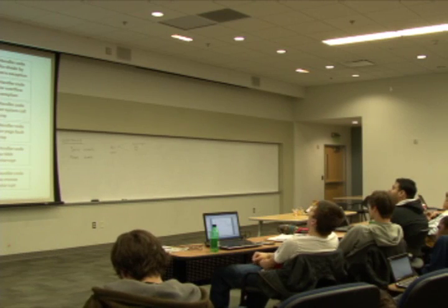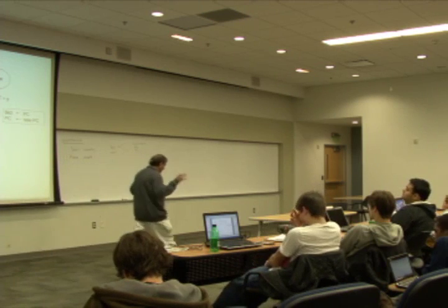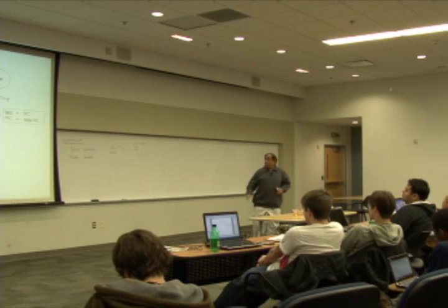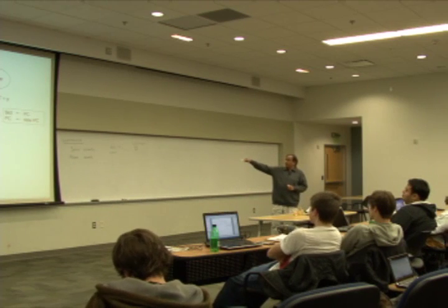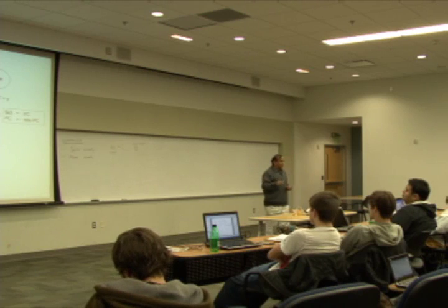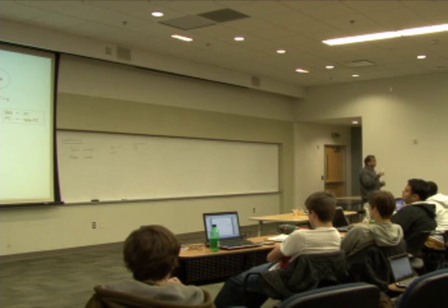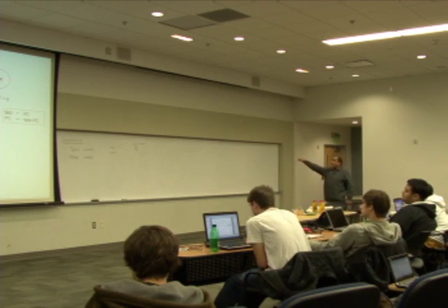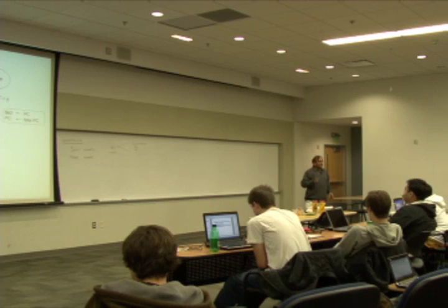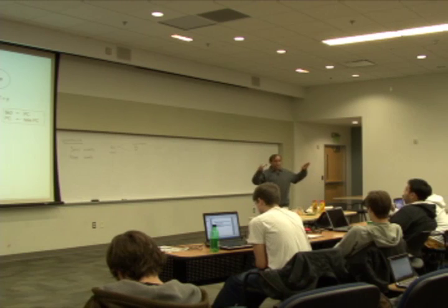So what we're going to do is modify the data path slightly. We've got the finite state machine. It used to go from fetch to decode, to execute, and then back. So this is your normal finite state machine that is doing your instruction execution. What we're going to do is, at the end of execute, I'm going to ask a question. There is a new line in the data path, which I'll call the interrupt line.